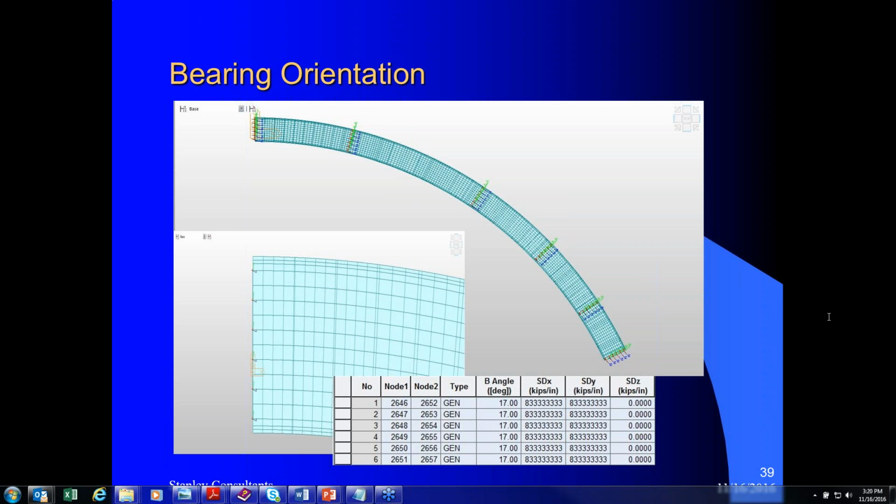Well, centrifugal forces are usually applied 6 feet above the deck, but you can get an equivalent force and moment. And I applied it at deck level, using an equivalent force system. Basically, it is a lateral force and an overturning moment. It just takes a little bit of calculation. It's 6 feet, so.